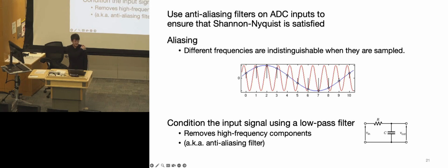And I think one of our classmates already mentioned there are anti-aliasing filters on the ADC output on a lot of devices nowadays. If it's one of the more modern ones, it essentially has an RC circuit that acts as a low pass filter. So anything below that cutoff frequency will be able to pass through this circuit. Otherwise, it's going to be blocked off, so those frequencies higher than what your system is capable of sampling would likely not enter the ADC chip you're working with.